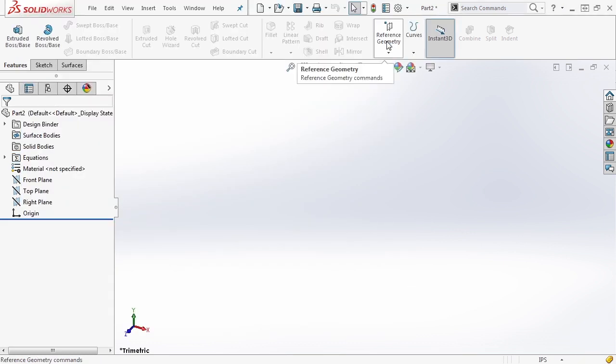All right, now we can get started creating some geometry. We're going to follow a basic process to create this part, but I want to note before we get started that there's not a single way to do this part. We're going to create several different extrudes to create the geometry we need, and then add a few fillets and things like that. But you could also create all of the geometry with a single revolve sketch. Because the revolve sketch is a little bit more advanced, takes a little bit more time, we're going to start by building upon it with individual features so that way you get comfortable with creating these features and applying draft and linking them to our global variables.